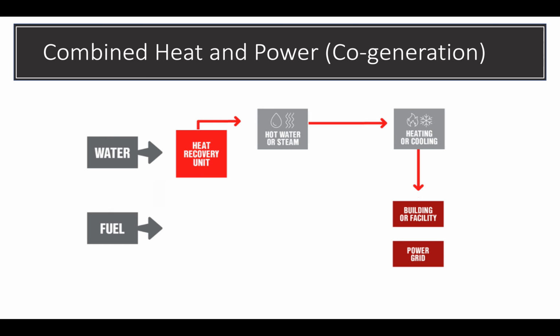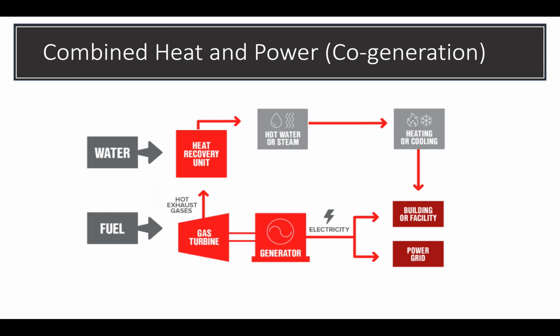Typically, a gas-powered industrial cogen plant will be located close to an industrial or residential hub to help ensure quick access to consumers and help reduce any transmission losses from the heat and power that's generated. The installation of industrial cogen offers really big increases in overall plant efficiency. Actually, it's not that uncommon to achieve up to 90% efficiency in cogen plants as opposed to 30 to 40% efficiency with the alternatives. I think you could see some of those efficiency numbers in that previous slide. So it's for this reason that cogen is often treated as a more environmentally friendly form of thermal power generation.